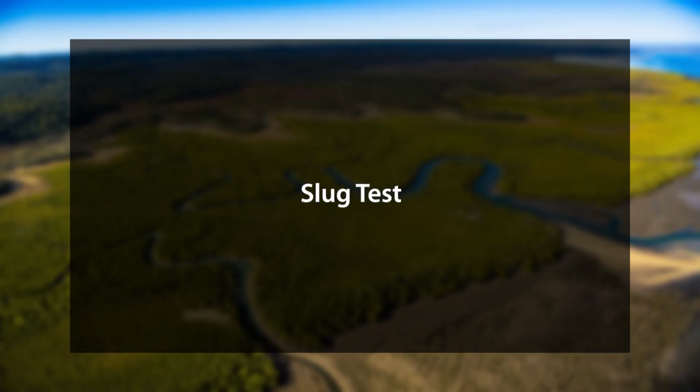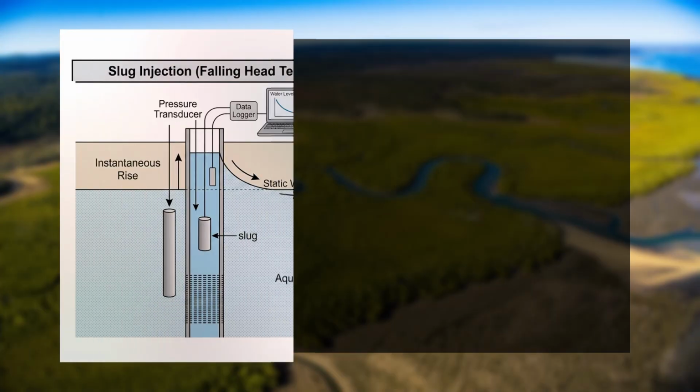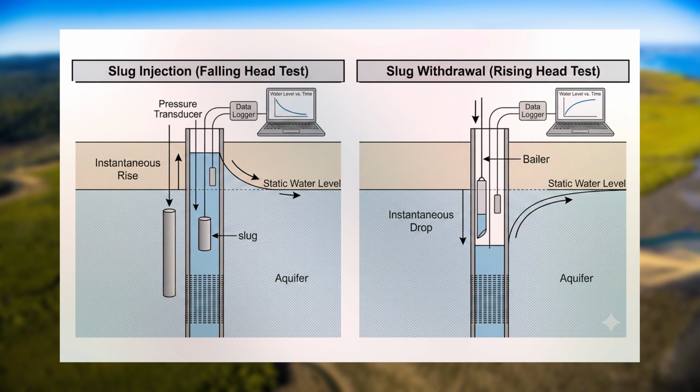Now, slug test. It is another quicker, less intrusive and more evolved method. In this, a slug of water is either added or removed from a well at once. This disturbs the water level in the well, which is monitored using equipment to estimate hydraulic conductivity at small scale.